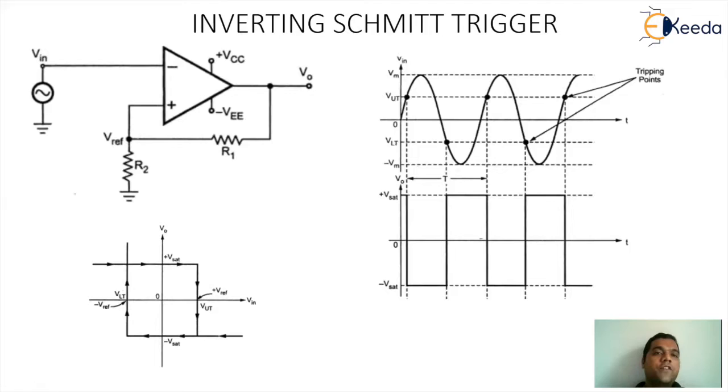So now if you observe carefully, the first circuitry is the inverting Schmitt trigger. The input is connected to the minus pin and the output is connected at pin number 6 of the op-amp if it is IC741. So assuming it's like a normal notation, this is our op-amp with an output value VO. There is a feedback path which is going from VO through R1 to R2 to ground, and we are getting a reference voltage that will be connected to the plus pin of the op-amp.